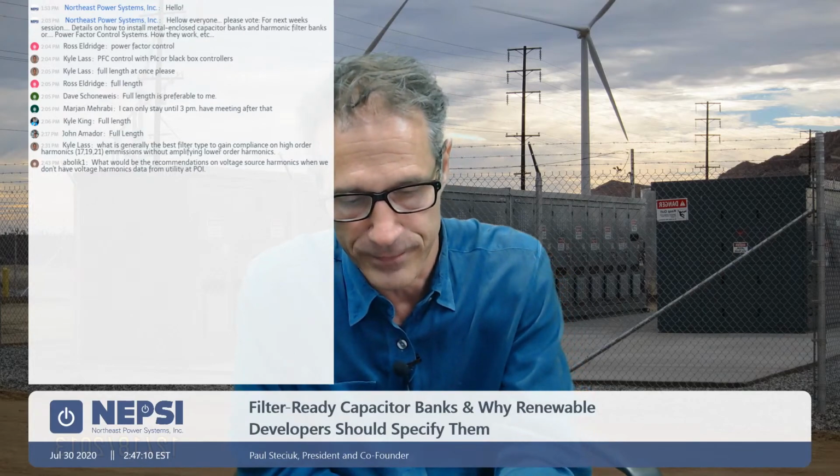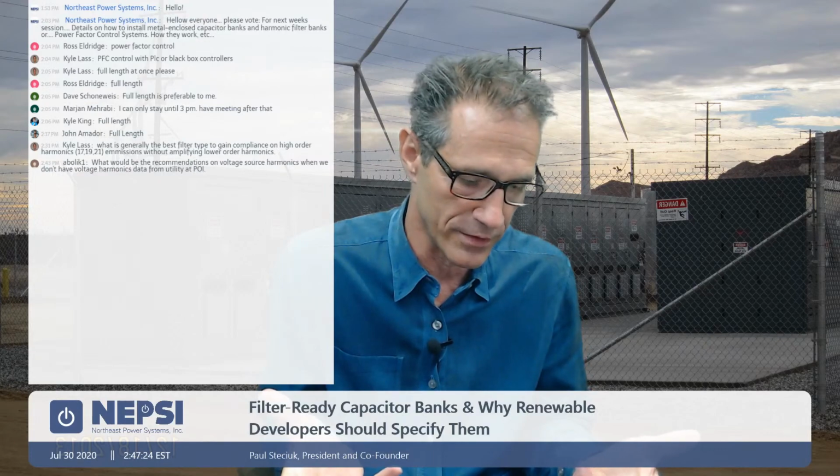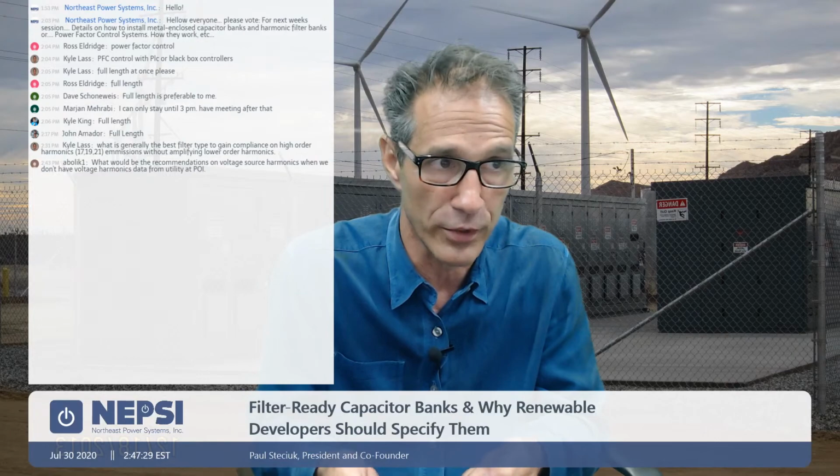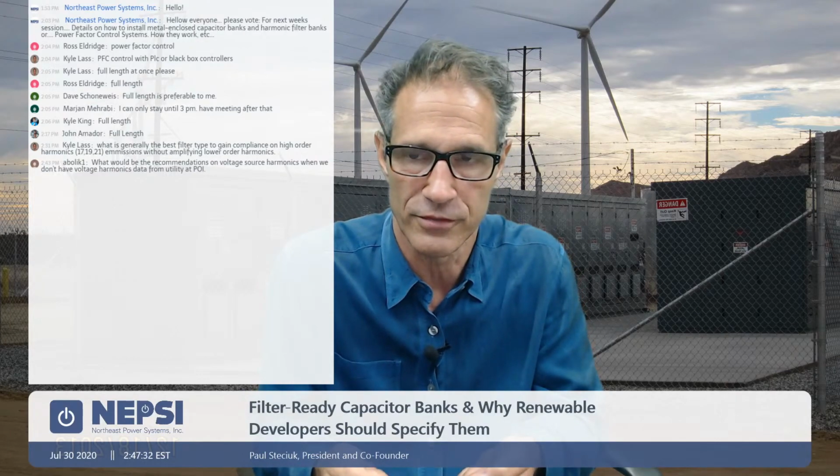What would be the recommendations on voltage source harmonics when we don't have voltage harmonic data from the utility at the POI? That's a good question, and I recently saw a study where somebody was doing 1%. So they would put 1% voltage source in their system. Say somebody has gone out into the network and done some network measurements at the point of interconnect, that high voltage transmission bus.